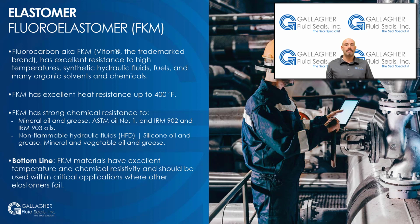Bottom line, FKM materials have excellent temperature and chemical resistivity, and should be used within critical applications where other elastomers fail. FKM has a higher price point than NBR. FKM does have low temperature limitations. Specific FKM compounds are available that perform better at low temperatures, but not as well as other elastomers.